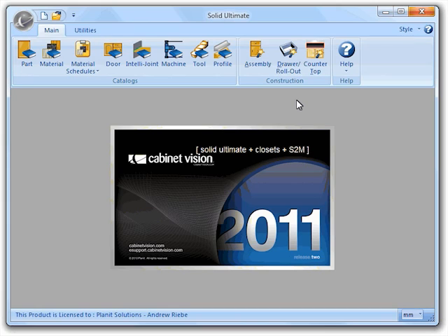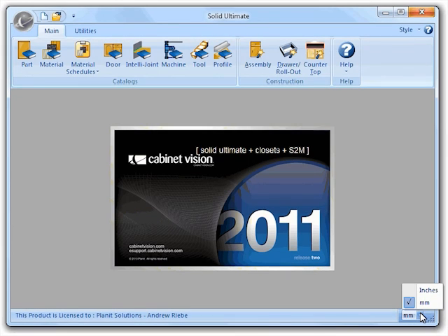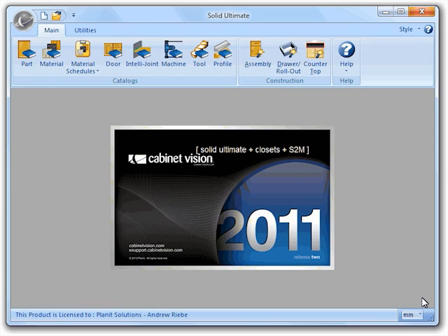As you can see, we still have our unit type being displayed to us, but what you should notice is the small arrow beside it. If we click on this arrow, it will bring up a new menu for us to change our dimension type. You can see that with this new menu, we have the ability to select either inches or millimeters. I'm going to leave it at millimeters for the time being. Now, if we click on the actual unit type being displayed, we will be given a menu to select the level of precision we would like displayed.